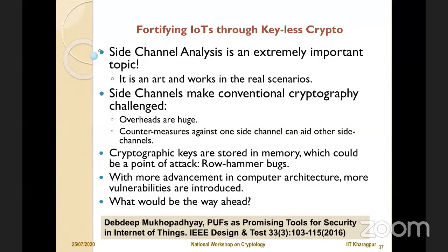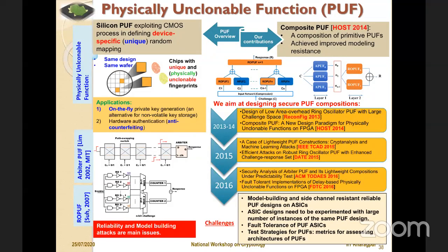I will try to give an overview of what a PUF is. The PUF is essentially a very promising hardware fingerprint. Ideally, if you have two devices and you implement the PUF on both, it should give responses which are statistically independent of each other. So the PUF is a hardware primitive which has identification built in upfront, in its very design.